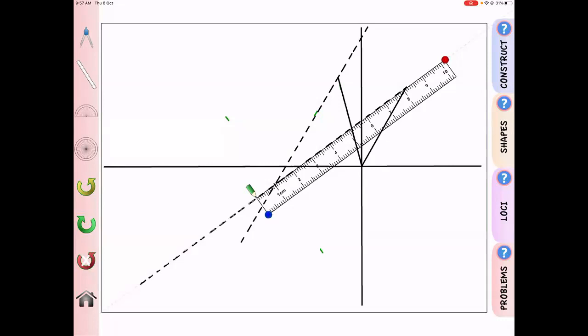Just wait, please. Let me just calculate it. 72 minus 15.5, that is 56.5, yes. So L3 equals 56.5. Did you get the point of how I calculated? I calculated from O2 to B1, right? O2 to B1 is crank plus coupler, okay? So I just subtract, from the total distance which I measured as 72, the crank radius, which is 15.5, so I got 56.5, okay?